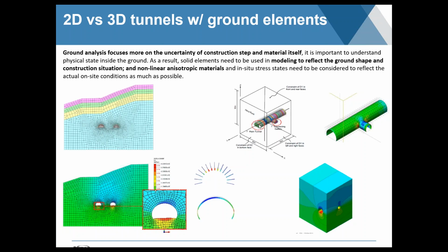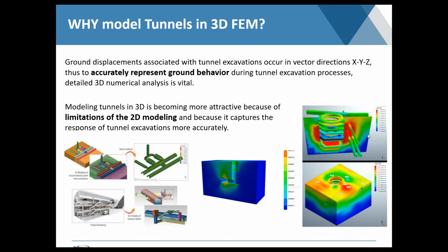you can now also start to determine the excavation stages or the excavation advances, not just the cut method, but how far each stage should be, what the irregularities might be, and once you're in 3D, you can really get into a very realistic simulation of anything you need to consider for the tunnels, like connections or terrain, etc. So the big benefit of modeling in 3D is that you can accurately represent not just the properties of the ground, but also how it's going to behave, especially during the excavation process, since we need to be able to determine the deformations or displacements in all three axes.